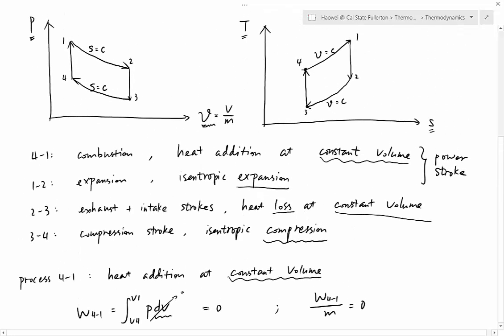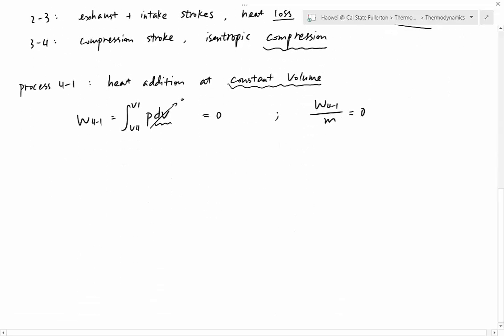We said when we convert the Otto cycle into thermodynamics, the whole thing would just be modeled as a closed system. So make sure you choose the short version of first law, which is Q minus W equal to delta E. And do not forget to add a subscript.